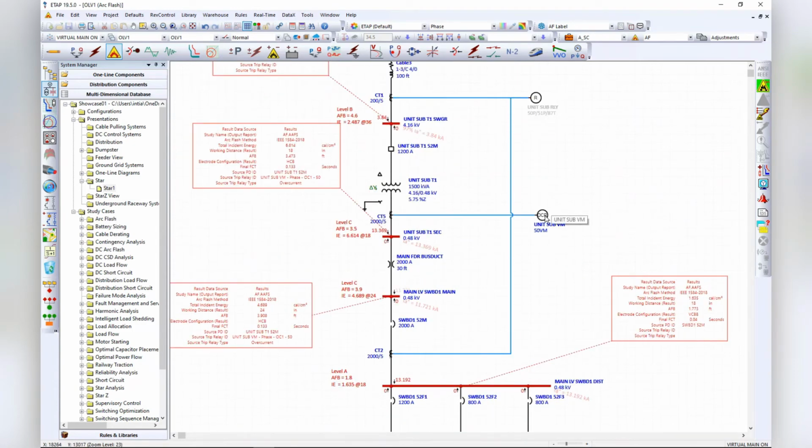I forgot to say something has to trip. Of course, the trip output on this relay is going to trip the primary side, and that's when the breaker comes into play. You've got to have a breaker for isolating that primary. You've got to do some trip on the primary side, energizing that transformer. So maybe this breaker is not next to the transformer.